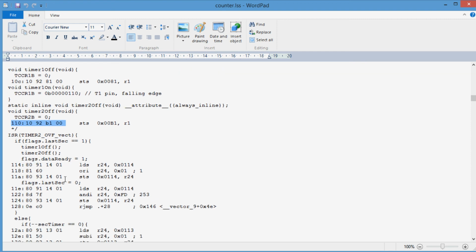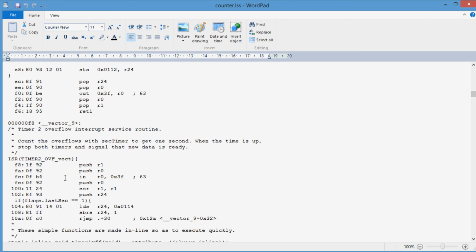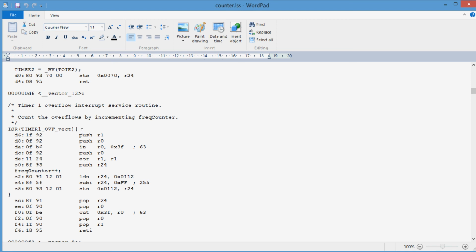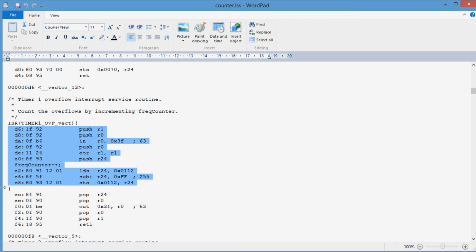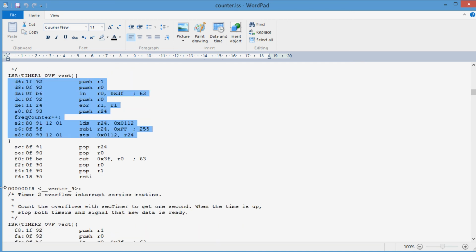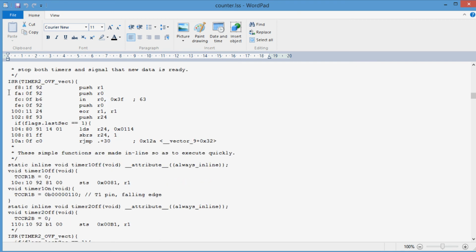Anyways, so it takes a little bit from the time the interrupt is actually generated. It goes through all of this stuff, down through here, and oops, I'm in the wrong one, sorry. It goes through this stuff here, down to here, and then finally it executes the instructions to turn the timers off. So it actually gets there pretty quick. But still, there's a bunch of time. Each one of these is 50 nanoseconds. So there's a little bit of an error in actually turning off the timer 1 and closing the window.